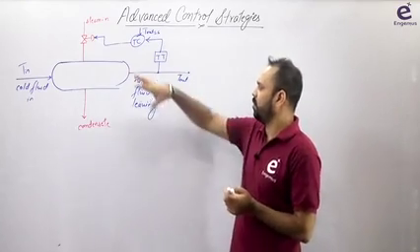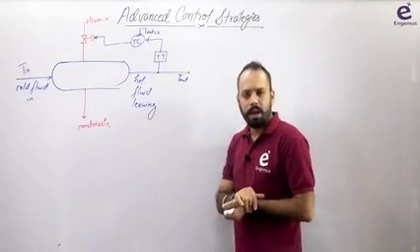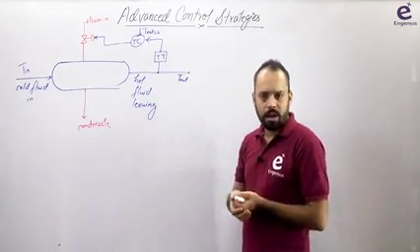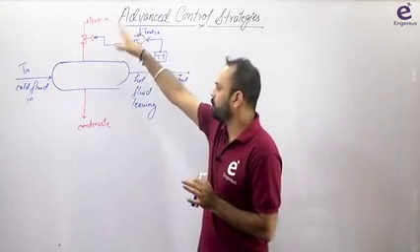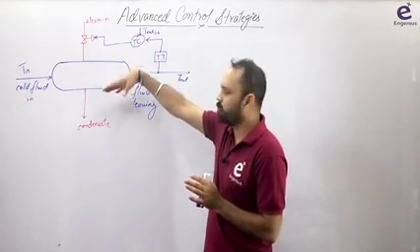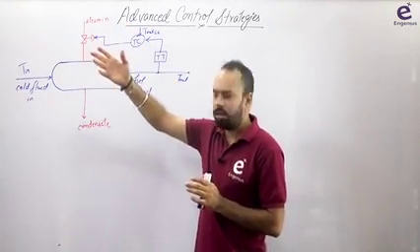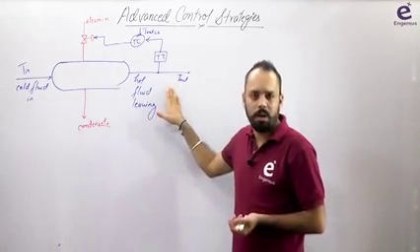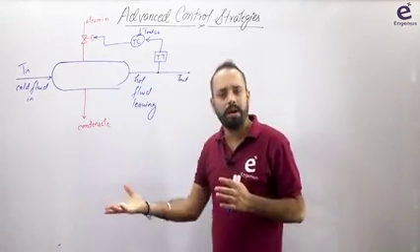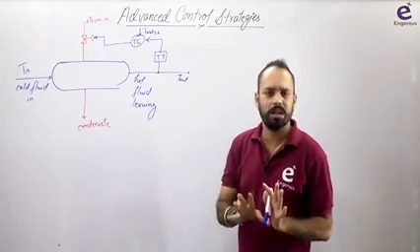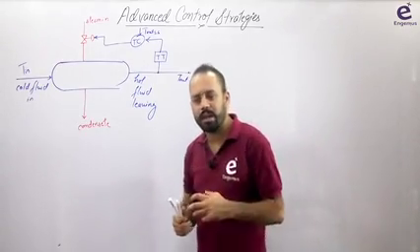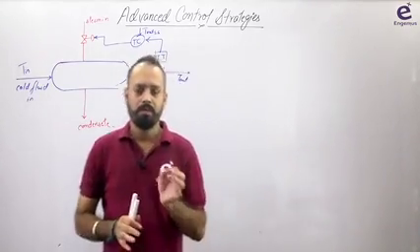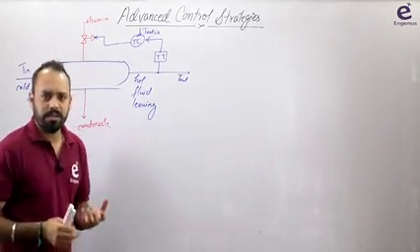criteria. If this steam is used for heating, you know that if the controller fails, you don't want too much steam to pass through the exchanger, because in that case you don't have any control, and in that case this temperature can exceed. And look, if temperature increases a lot, there is a problem; if it decreases a bit, it is not as much of a problem. Have you ever heard that temperature dropped so much that a blast happened? That doesn't happen. So these are the logical explanations, these are the logical things.